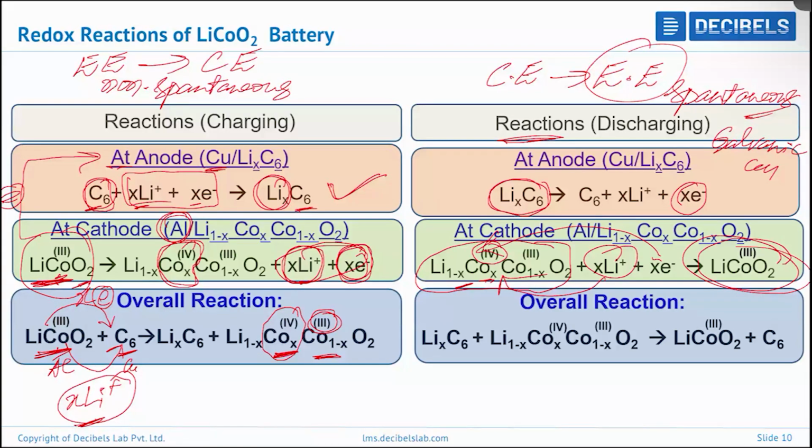So this is called one cycle. Like that, again we go for charging and discharging, and we can expect 1,000, 2,000, and 3,000 cycles. That depends on the battery chemistry. Upon charging and using for several cycles, because of structural damage inside the cell, the expected voltage cannot be achieved. It may drop down with the usage of the battery.